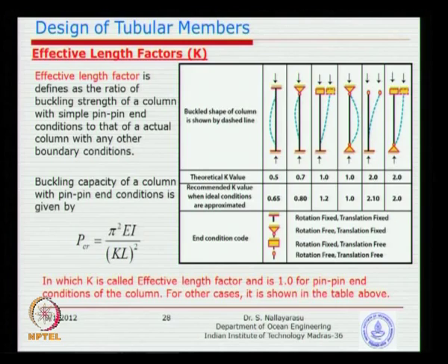The boundary conditions are reflected by the so called boundary condition factor. Euler buckling length, buckling factor, whatever you call it, is the means of treating the edge conditions to transfer higher load or lower load. You can see here the pin condition is nothing but rotation is allowed, translations are not allowed, whereas if you go to fixed conditions, 100% restraint on rotations as well as the translations.